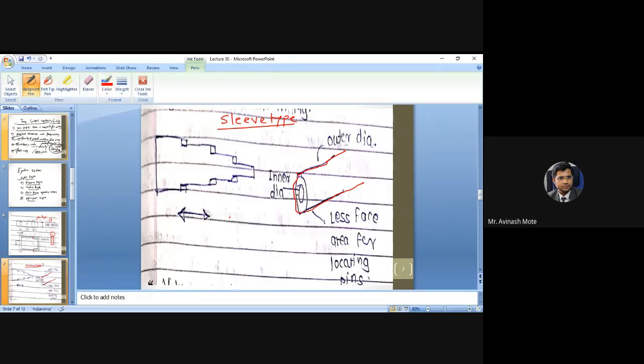This kind of products where products are hollow, the effective surface area is very less, so we cannot go for the pin type ejection system. So we have a sleeve for that purpose. What is the sleeve? Here it is shown. A bar, or you can say a different cross section, but with different size in one piece.